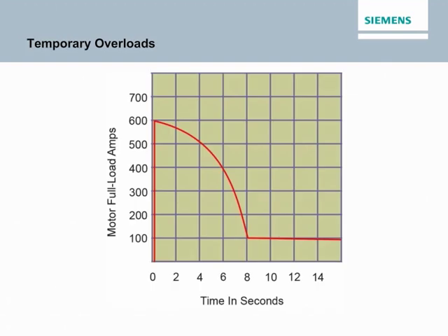In the previous example, the overload resulted when a circuit exceeded its rated capacity for an extended time. In such a situation, an overcurrent protection device should shut down the circuit. A different response is required for a short duration overload. In such a situation, it may be undesirable to disable the circuit. To understand this better, consider what happens when an electric motor is started. When most motors start, they draw current in excess of their full load current rating.